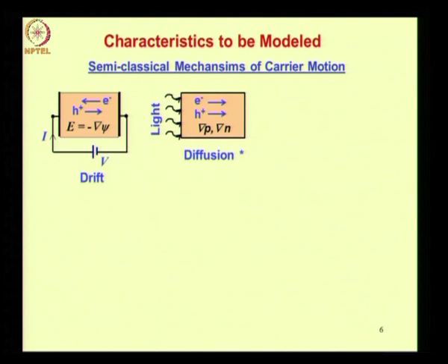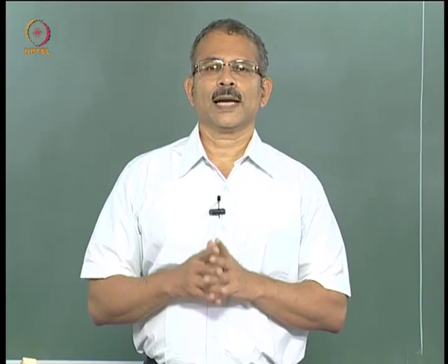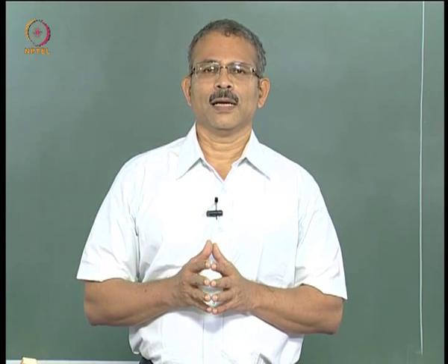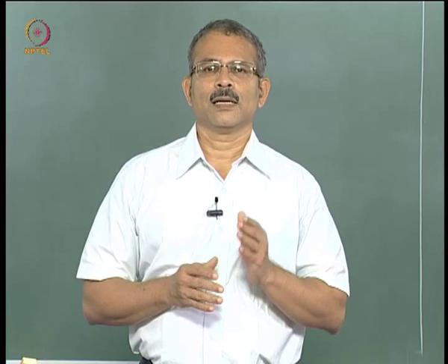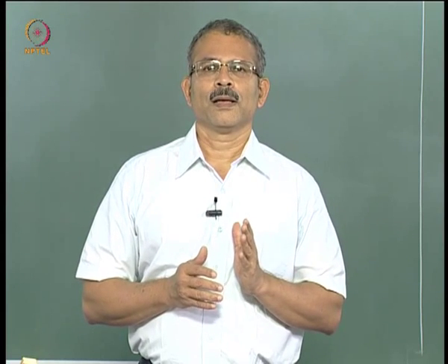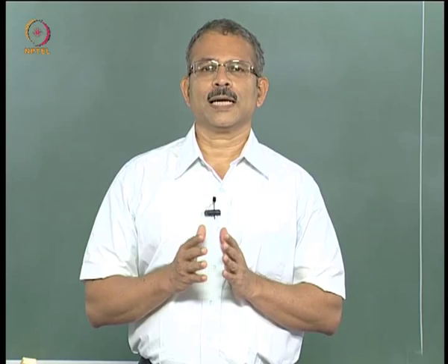So what you find is both electrons and holes are moving to the right because of the concentration gradients of holes and electrons, shown as gradient of P and gradient of N. Because gradient of P and gradient of N is created in the sample by illumination of the left surface, electron and hole diffusion currents are maintained.